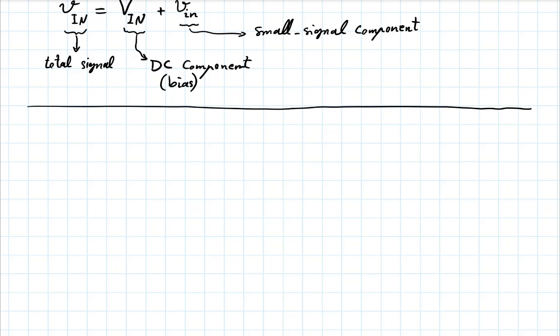And now you take the fine tuned knob of the power supply and change your 3 volts to 3.001 volt. Okay? There you have applied a small 1 millivolt signal on top of that 3 volt signal, and you've left it there. The response of the circuit to that 3.001 volt signal can be understood as its response to the 3 volt signal plus its response to the 0.001 volt signal, right? Even though that change is not AC in time, it's small. It's still a small signal variation.